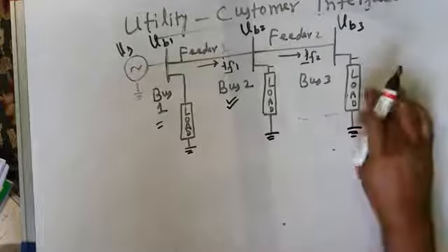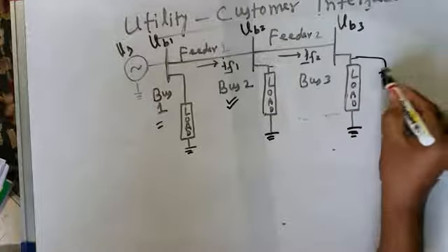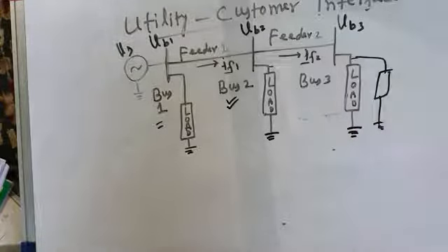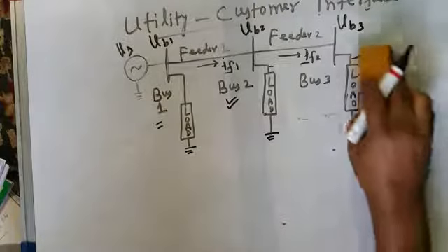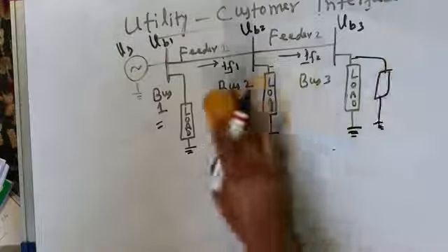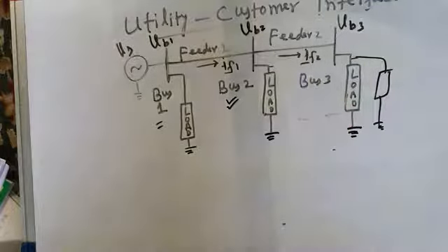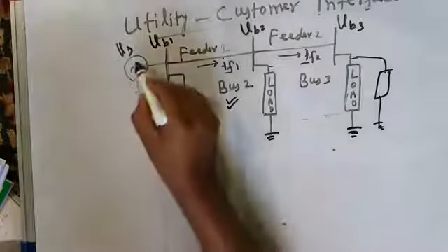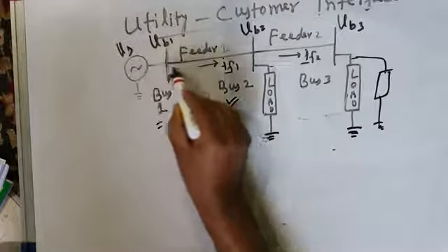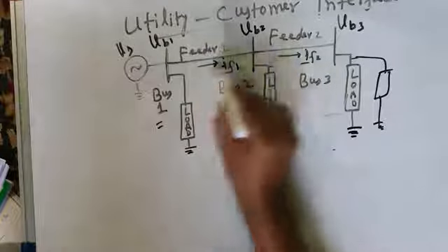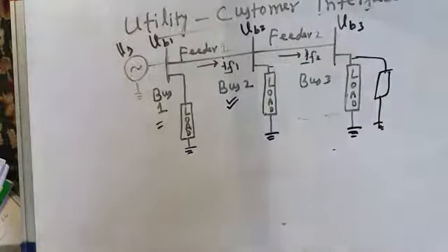And therefore load compensation, the shunt connected compensation device, has to be connected by the customers of the polluting loads, which are called custom power devices. Okay, fine. If they agree to install this, all these problems will get solved. But there may be other problems which are voltage related problems. Voltage related problems means that the voltage coming from the source to various buses may itself be distorted.